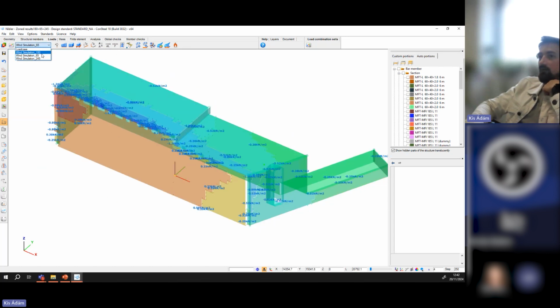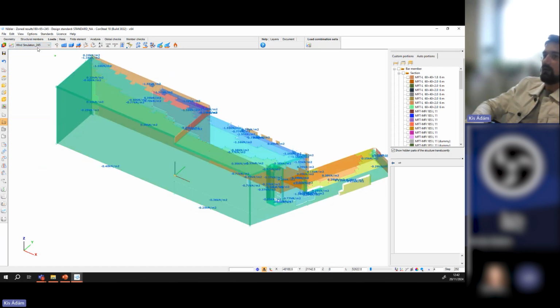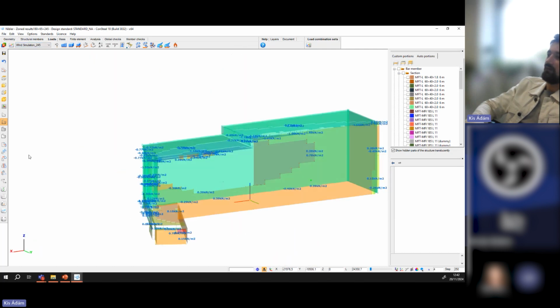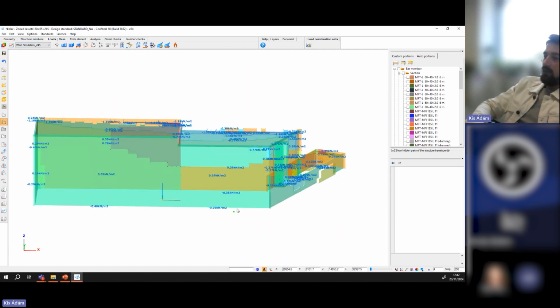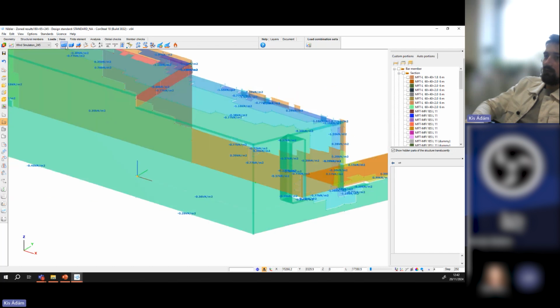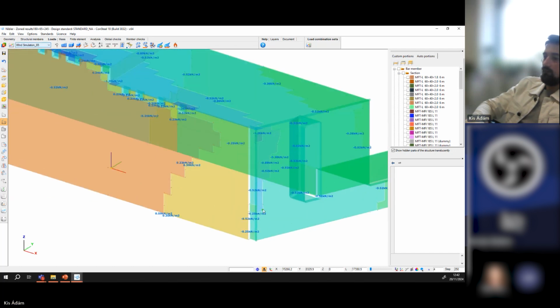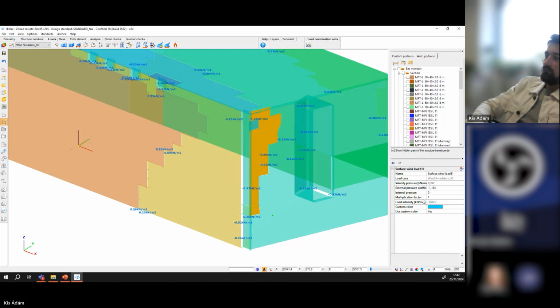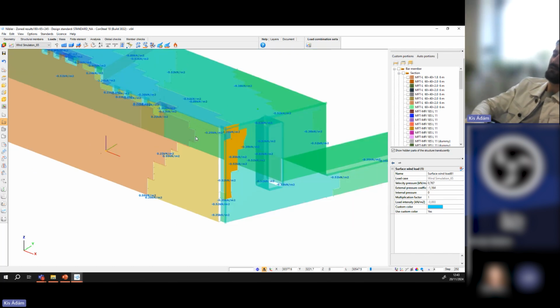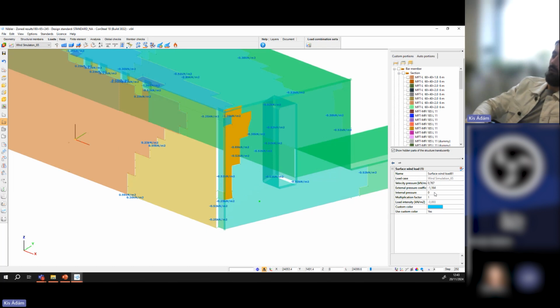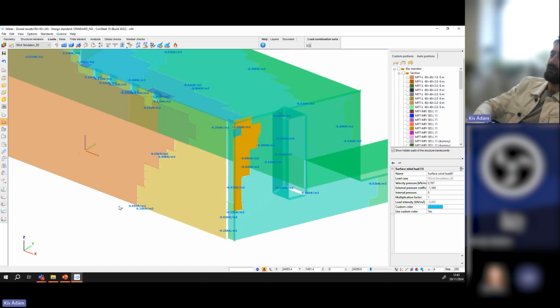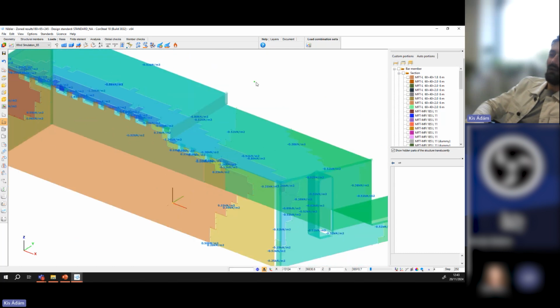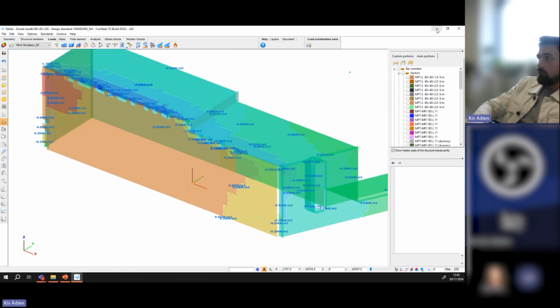orthogonal directions, but for instance, we have this 245 direction. So again, we have every zone here with its own velocity pressure value according to its height, or the load transfer surface's height. We have external pressure coefficients, which we can compare. We have a load intensity. It is colored accordingly. So these will be the results for this case, for example.